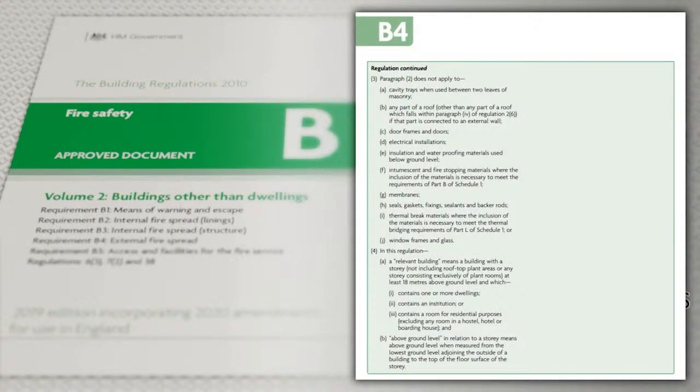For example, intumescent materials react to fire by definition, and so cannot be non-reactive by the very nature of the material. This type of material includes intumescent paints which protect steelwork, some cavity barriers, particularly in rainscreen cladding systems, and our own fire shield breather membrane.